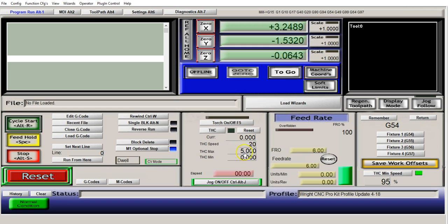You can make other fine-tune adjustments here if necessary. We could always just make sure that the Z-axis never goes below a given point. So let's say 0.0, let's go 0.6. Enter. Now the Z-axis will never come down below that point there. So make sure that that's the case. And the system is actually going to regulate that for you. But by doing this, we do lock that position so it doesn't go below that given value.